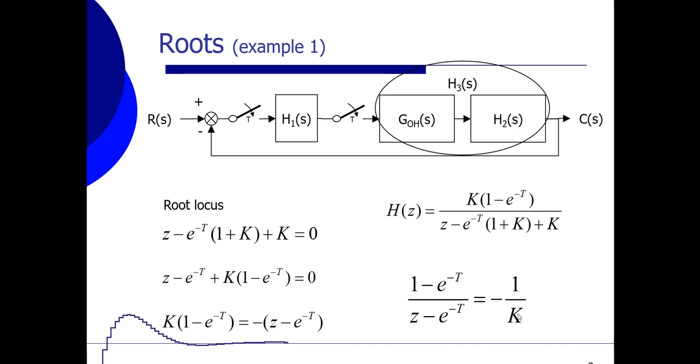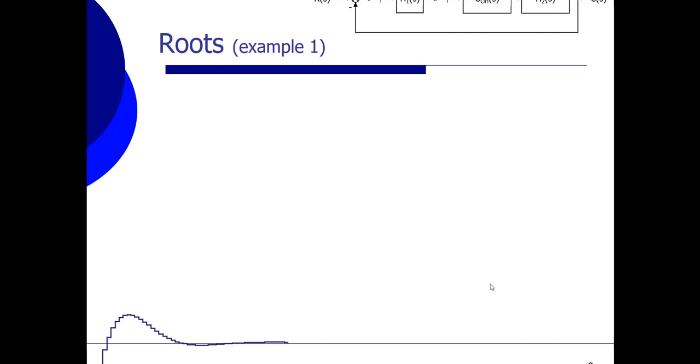So what are the basic rules of the root locus? Well, there are two rules which are always important. The first rule is that every branch of my root locus starts in a pole, and every branch ends in a zero. But when there are fewer zeros than poles, then that branch could end in infinity. That's rule number 1. And the second important rule is that you have to define which part on the real axis belongs to the root locus.